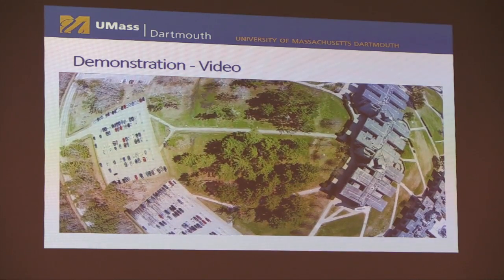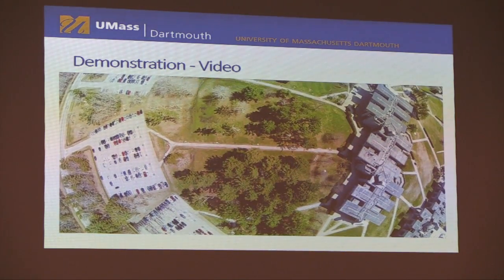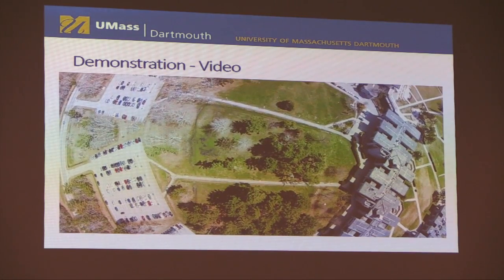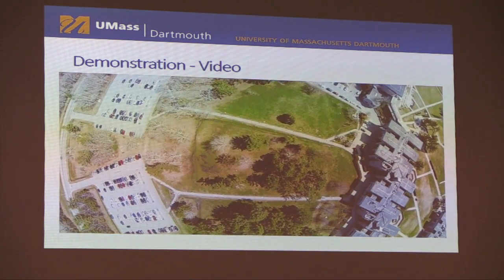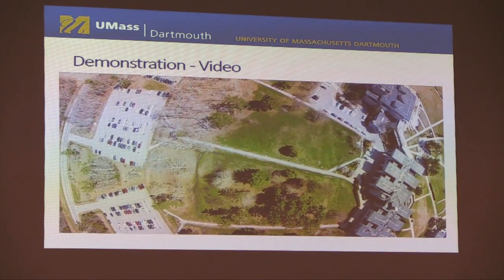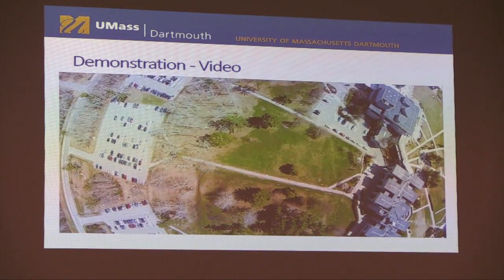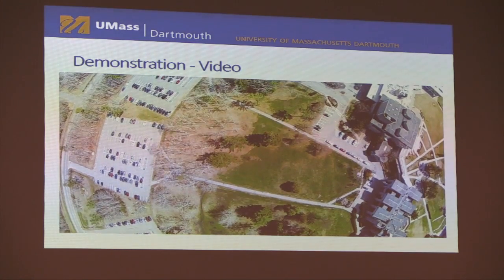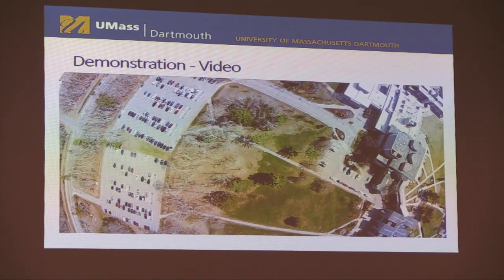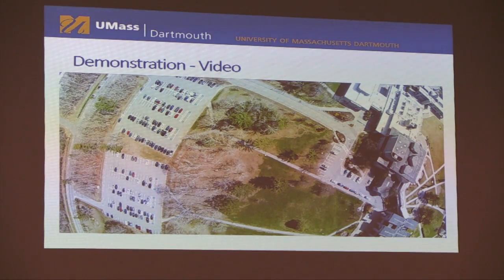We ask that the customer puts in a 5-second delay at the first waypoint and a 5-second delay at the last waypoint, because it's easier to process images when you're, first of all, in the sky and you're not taking into account the drone taking off or landing or any other land that's not necessary. This is because it's harder to do transformations when things aren't at the same height and things look different, and you get really bad results because we tried it like that.